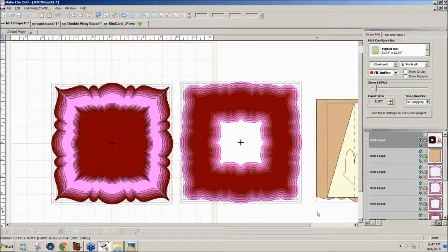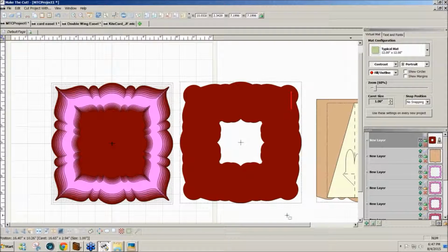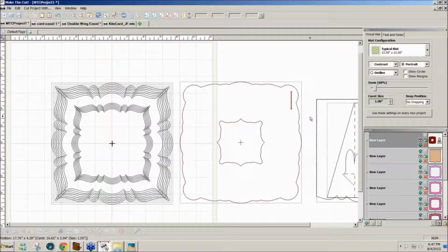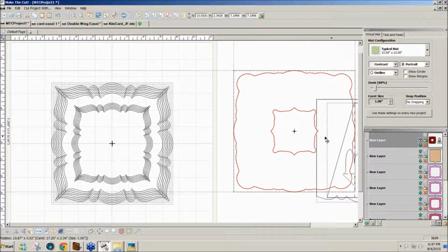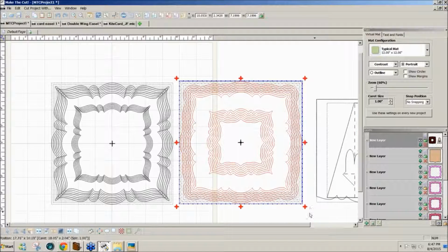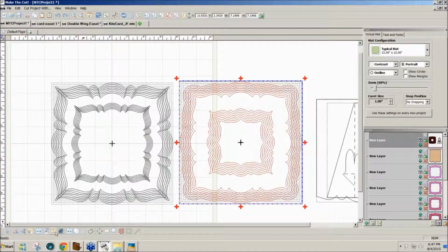And I do the same thing that I did there with the layers. Again, I'm going to just break apart everything and view by outline. And so now I can, again, start with, I'm going to send the inside ones to the front if I can. I'm going to break these again. I hit the wrong one. I hit weld before. Break. Here we go.